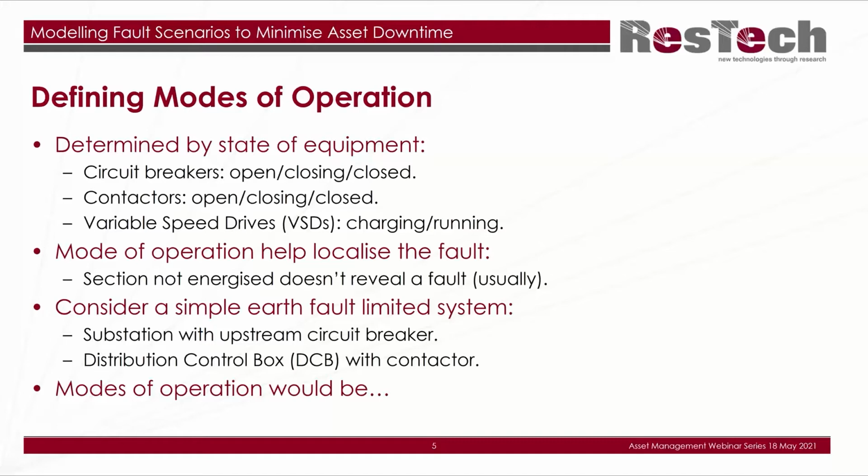And of course, this is actually quite good because knowing what the mode of operation is helps us locate or localize the fault. Generally, a section that's not energized doesn't reveal a fault. Okay, there's no power to that section. Even though a fault might be present, we don't necessarily see it.